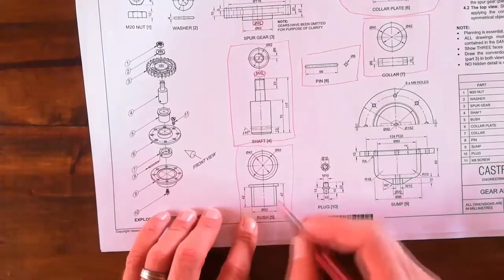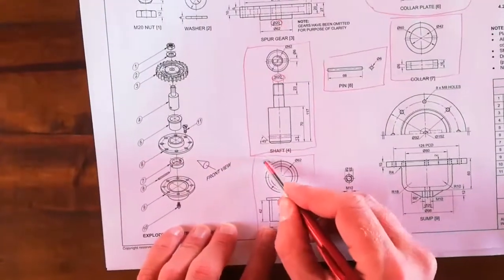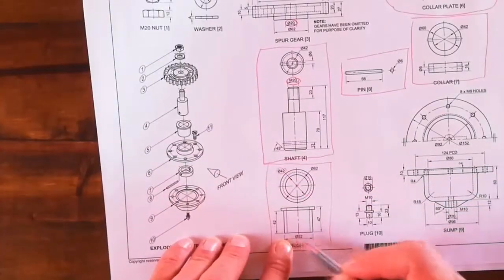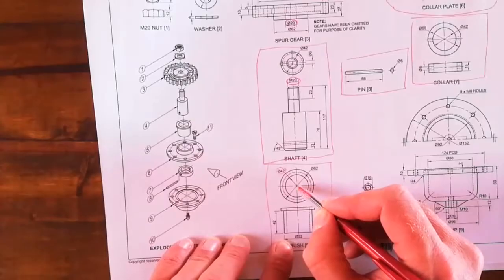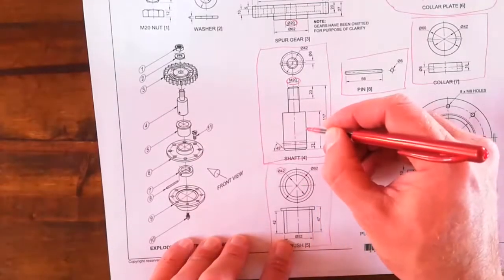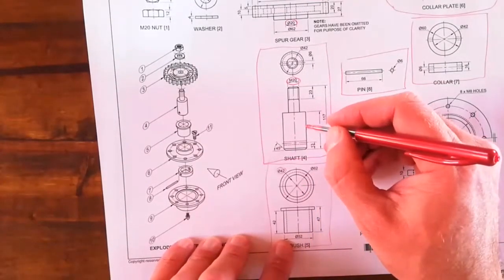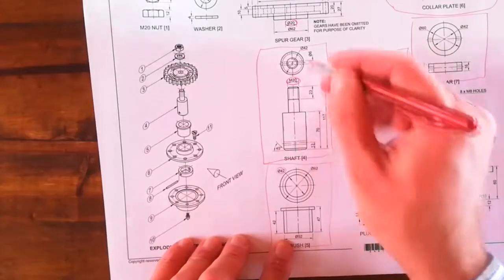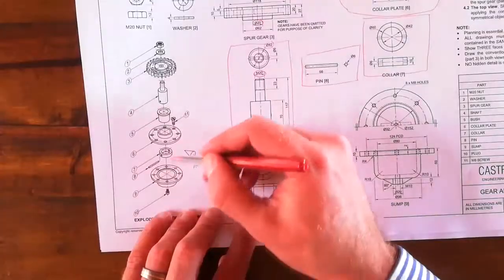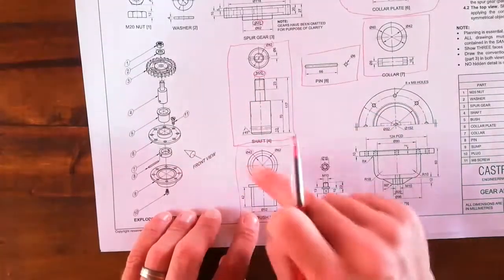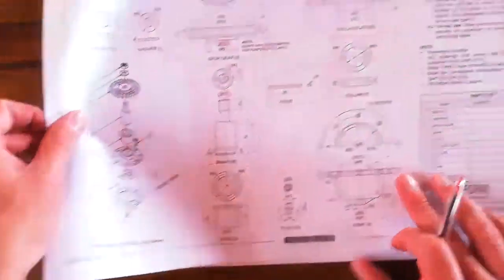Let's look here. It's an inner diameter of 42, an outer diameter of 52. But it's this diameter 42 that's important for you to double check. That's exactly the same as the outer diameter of the shaft. There you can see that's the 42. So take time to see how these parts fit together, and the measurements will line up. I can promise you that.